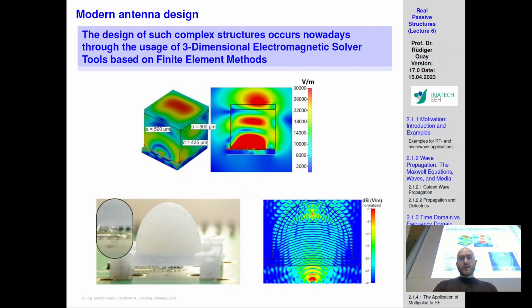Modern antenna design, as is modern circuit design anywhere, is done by using EM simulators, 3D EM simulators. We saw an example of that when I showed you a bit of CST and a bit of ADS, and how to use ADS and CST in combination. You begin in ADS, you have a schematic, you design components with predefined model definitions. You use a lumped definition of a capacitor, whatever the case, to make an RC network, to make a matching network for your amplifier.